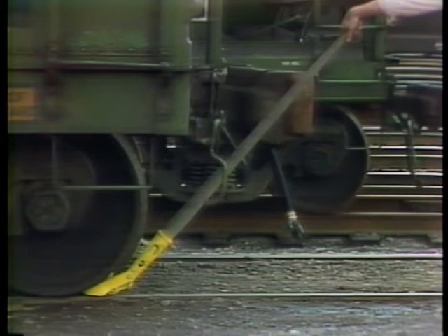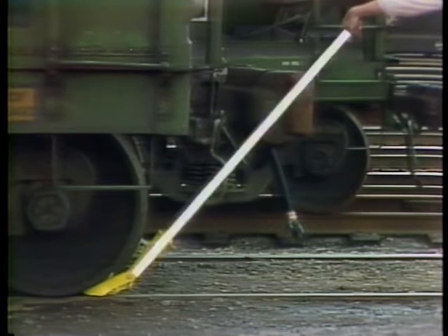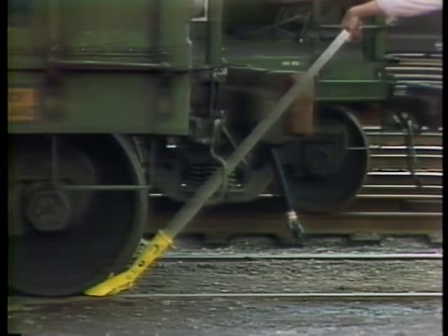The important thing to know about force transformers is how much of an advantage they provide. In most cases, this is very easy to determine because there's a clue right in the transformer itself. To find the advantage, you can measure distances, measure sizes, or count things. The distances are the distance the input side moves compared to the output side. That could be the distance the arms of a lever travel.